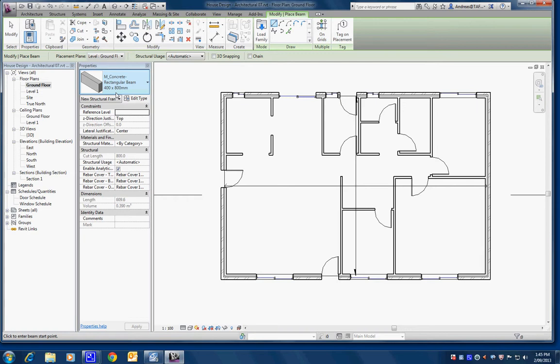But because we've got a 30mm rebate in our wall system and the external brick wall, we want to drop it by 30mm up the top. So what we need to do is create one that's only 470 deep. Eventually the engineer will put some internal ones in here, and they will start at the right level, and then we should end up in the right spot in the end. So we'll make the other ones 500.